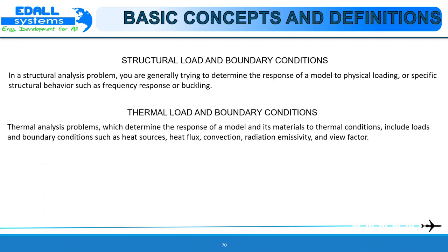Thermal loads and boundary conditions. Thermal analysis problems determine the response of a model and its material to thermal conditions. Loads and boundary conditions include heat source, heat fluxes, convection, radiation, emissivity, and view factor. Note that the temperature values that often form the output of a thermal analysis may subsequently be used themselves as loads in other types of analysis, such as structural problems. The use of output quantities as loads is supported in Patran using a field capability known as FEM fields.